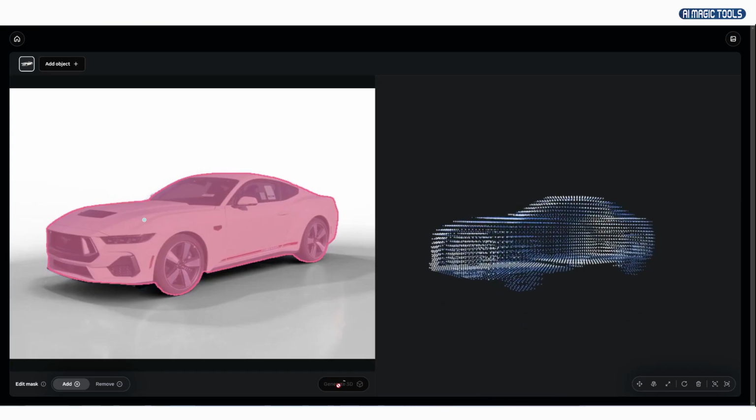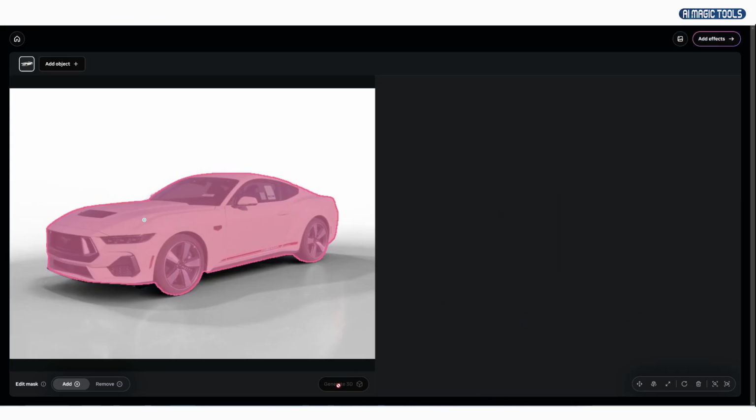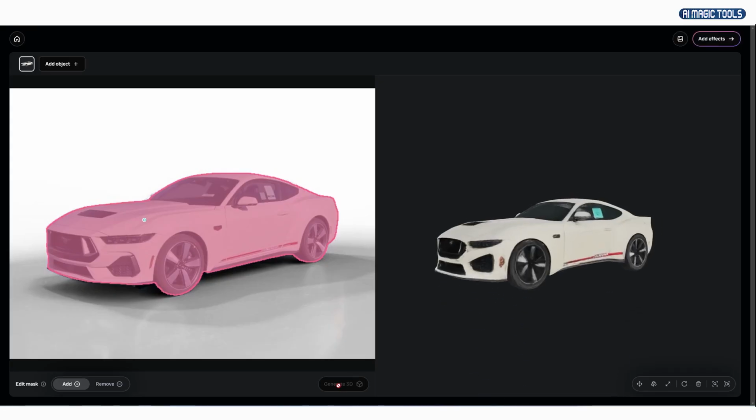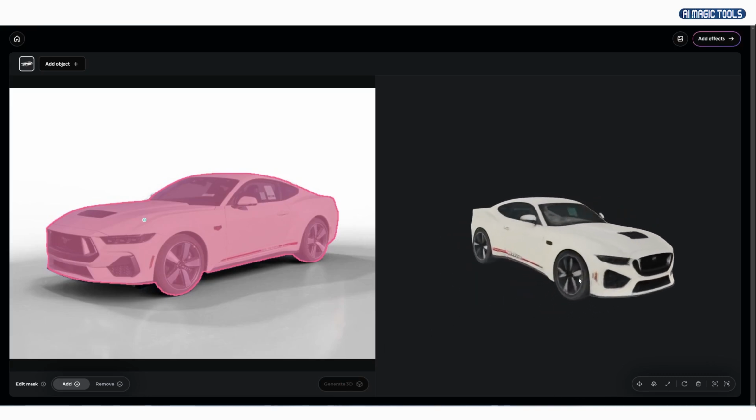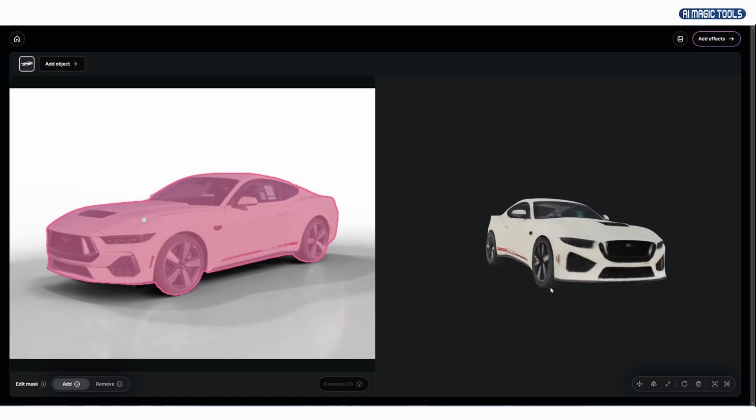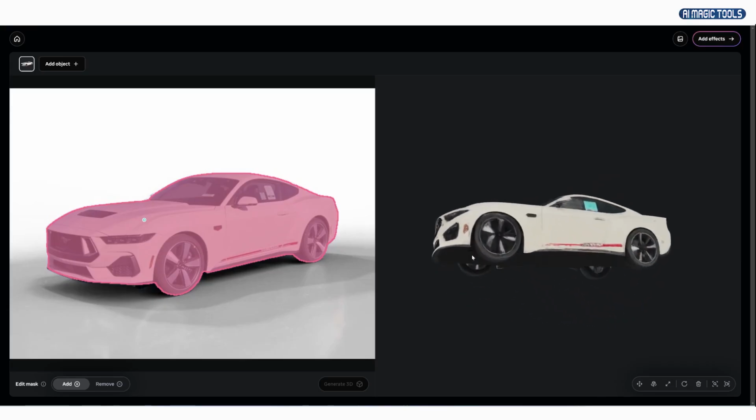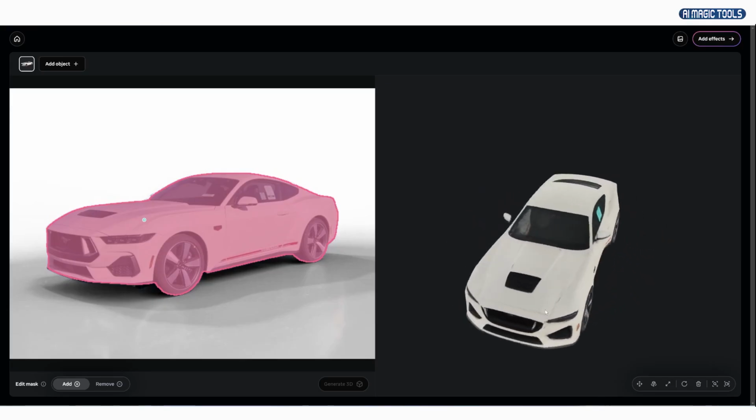So, how do you actually look at this thing? Well, the best free tool out there for this is Blender. It's super simple. You just open it up, go to File, then Import, and find Wavefront .obj. Select your mesh.obj file, and that's it. Your creation will pop right up on the screen, ready for you to spin it around and check it out.